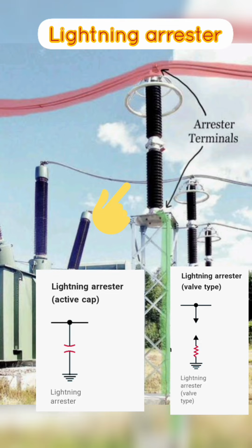It is important to note that lightning arresters are not a foolproof solution, and they can still fail if subjected to a particularly large surge or if they are not properly installed or maintained. For this reason, it is essential that lightning arresters be inspected and tested regularly to ensure they are functioning correctly and that any defects or damage be repaired promptly.